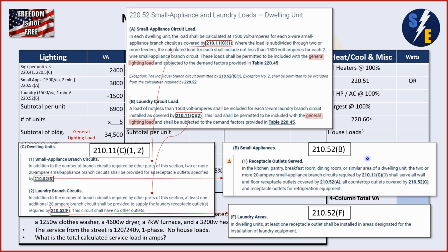It's accepted here. Another one would be like under cabinet lighting or upper cabinet lighting where the lights plug into receptacles. Those receptacles are accepted from being on the small appliance circuit. Anyway, you can read that exception in your code book, and that might clear up some questions you may have on that. But that takes care of our small appliance circuits. Moving on, we have laundry next.